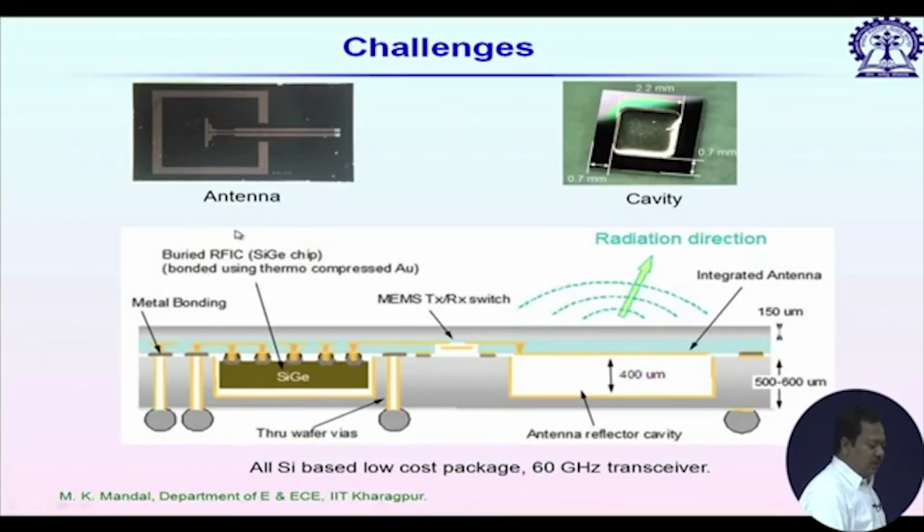So, this is showing a typical scenario, one on-chip antenna. You can see the copper part fabricated on silicon, but the problem is that if we directly fabricate one antenna on silicon, most probably it is not going to radiate anything. Almost all of its power will be absorbed by the silicon. So, then how can we make it radiate?